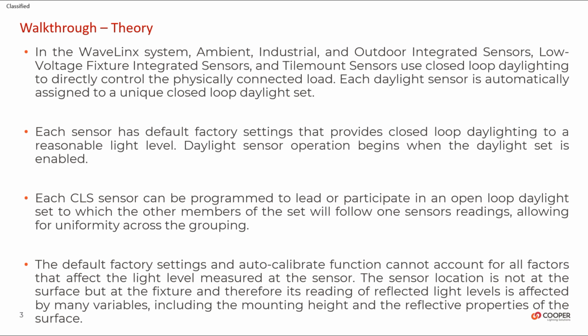Each CLS sensor can be programmed to lead or participate in an open-loop daylight set, in which the other members of the set will follow one sensor's readings. This allows for uniformity across the grouping.